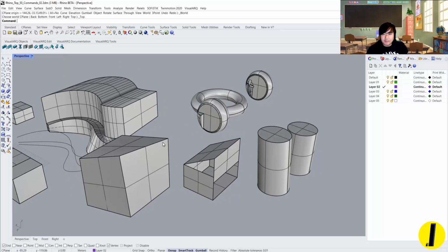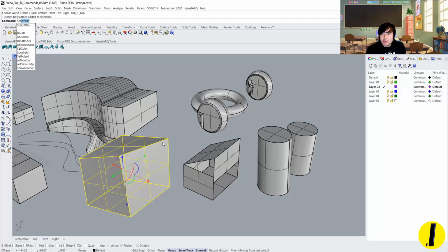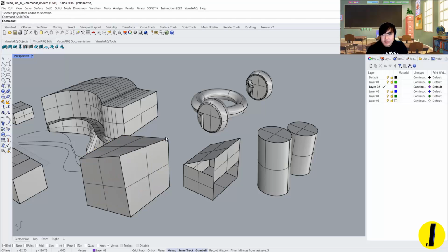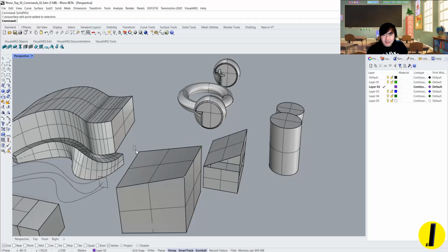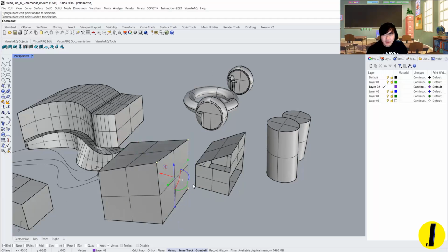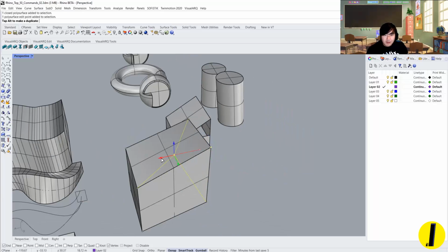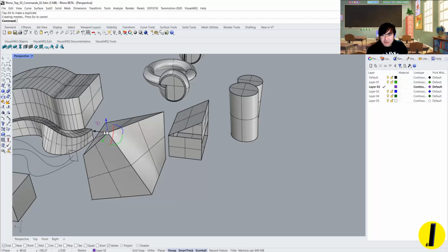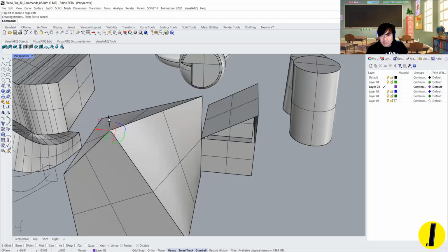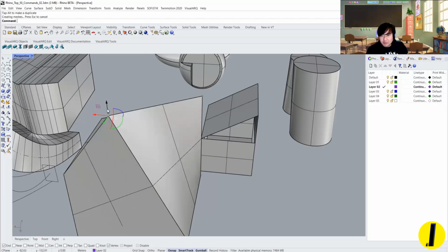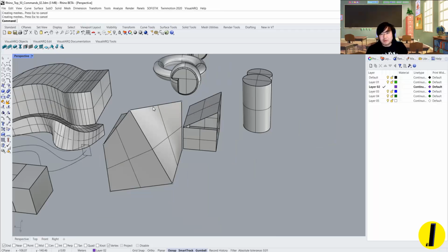It's called solid point on, and you can see we can select the vertex or vertices and simply manipulate the points that you select. Also with this gumball, you don't have to drag the arrow, you can also click and give a distance, for example 1 meter, and it goes 1 meter.